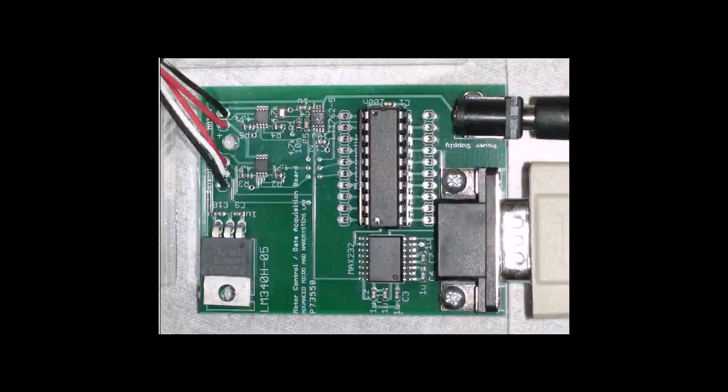To command the microchip microcontroller to deliver a specific pulse-width modulated duty cycle to the motor, the host PC must send the microcontroller an 8-bit value with 7 bits representing the duty cycle and 1 bit representing the sign of the signal. The motor is driven by an H-bridge, shown on the printed circuit board, which allows current to flow both in the positive and negative direction through the motor, allowing for forward and reverse motion of the pendulum. When the microcontroller receives the signal, it will correctly apply the duty cycle as dictated by the PC.